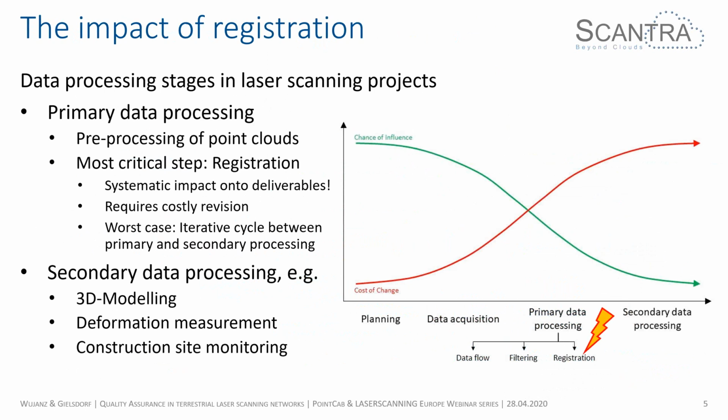And now you can see that the registration is quite dangerous because it has a systematic impact on all deliverables. So in other words, if your registration is wrong, your deformation measurement will be wrong, your construction site monitoring will be wrong, and that's actually what you're trying to avoid.